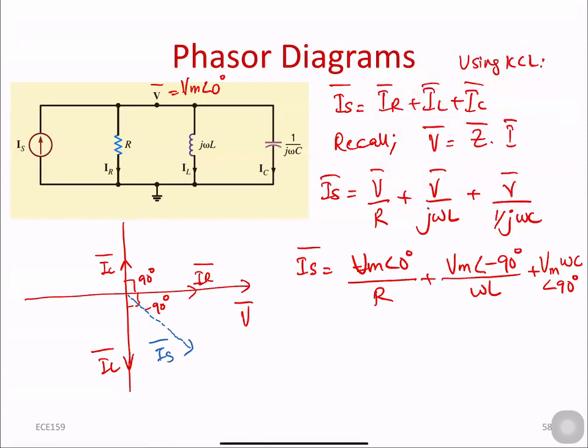Please note that what I have done is the magnitude here. So this value is the same as this value, because the resistor, IR and IS, will have the same resistive component, right? Only the J part, or the imaginary part, is contributed by the capacitor and the inductor. So that's why we have exactly the same value for the resistive components. So R plus JX is going to be the solution of IS.